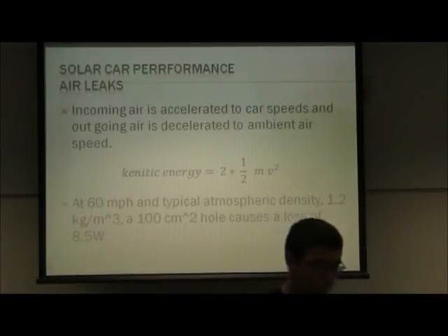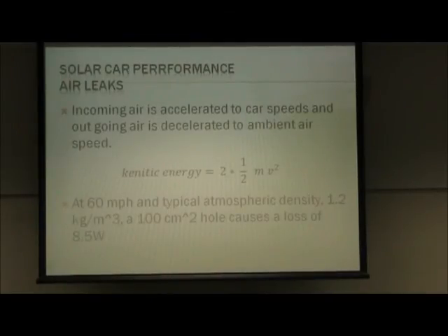So what does that say you need to do? If you're really going to race, you want to tape that array shut, make it smooth, just leaving room so the driver can exit. But you also need to have closed wheel wells so you don't have air going in and out, and as few small holes inside the wheel wells as possible. This isn't even the turbulence in the wheel well. This is just the acceleration and deceleration.